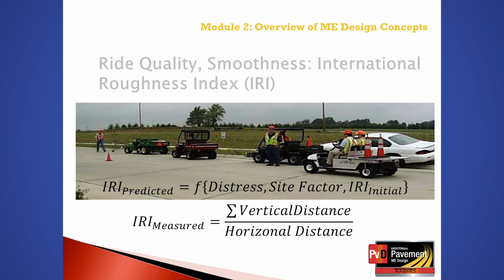The IRI is dependent on the individual distresses for a specific pavement type predicted by the PMED software, the initial IRI at construction, and a site factor. All of the variables for the different pavement design strategies are presented and discussed in Modules 5, 6, 8, and 9.